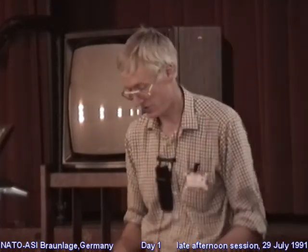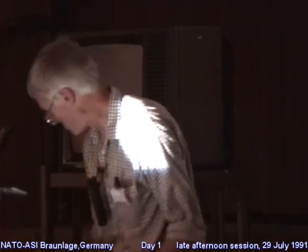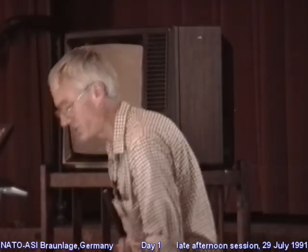So that's why I've put that often the adhesion term in friction, or the tangential interaction term, whatever you like to call it, is far too small to account for the observed frictional force, but it can trigger a large increase in the plastic strains involved. And this was pointed out very clearly in 1981, I think it was, by Professor Johnson. So let me take up then this point on the right, that surface forces can trigger bulk energy losses.